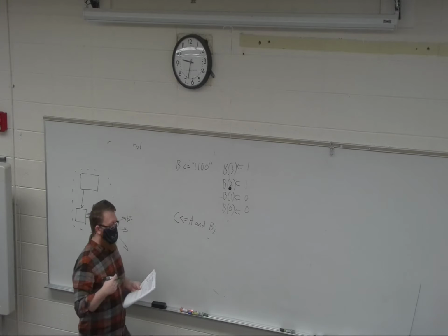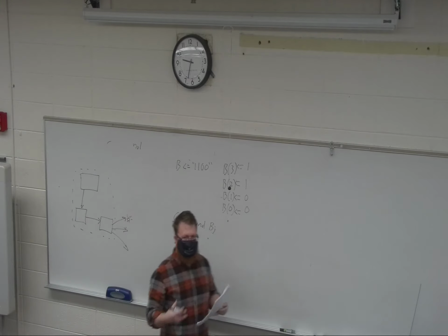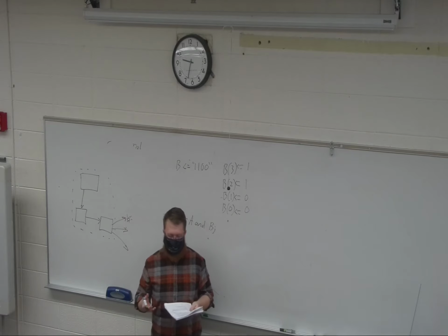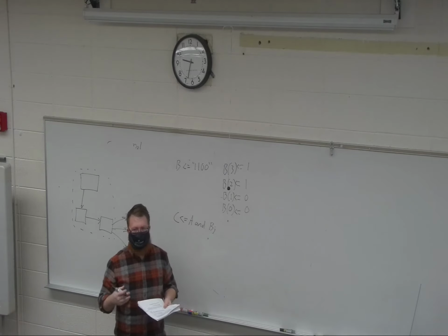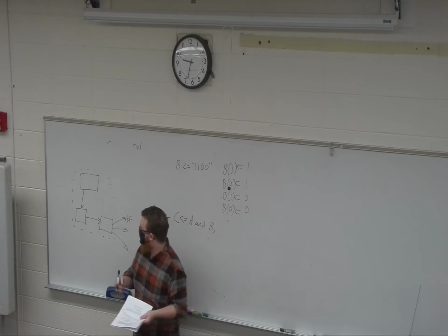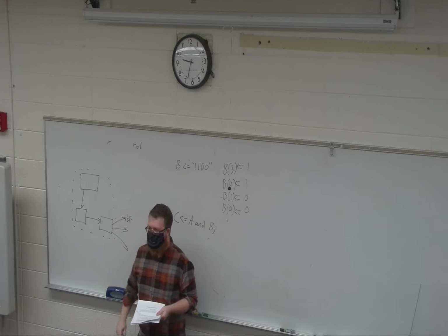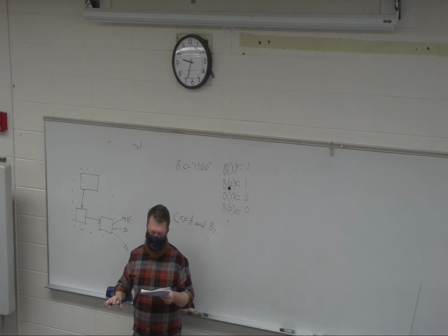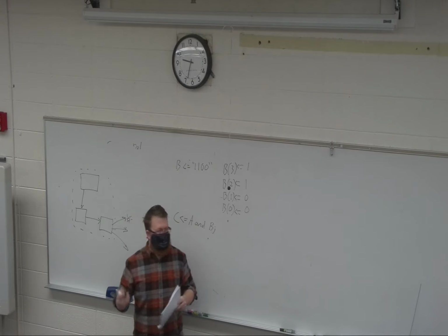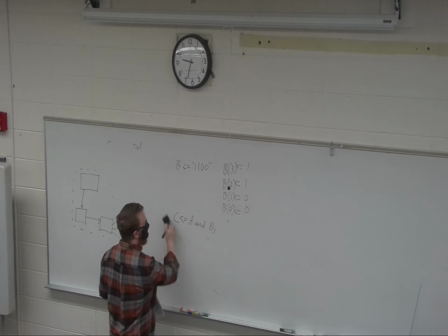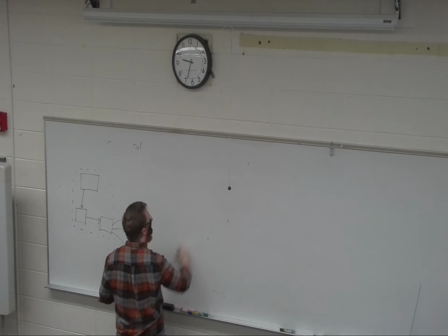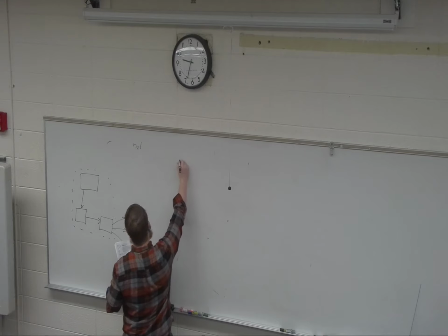Okay, so that's the basic structure of really simple code for VHDL. But when we want to start putting this together into what we call modules, that's what a block is going to be. And you can put a module and a module and a module. And we start with an entity declaration.